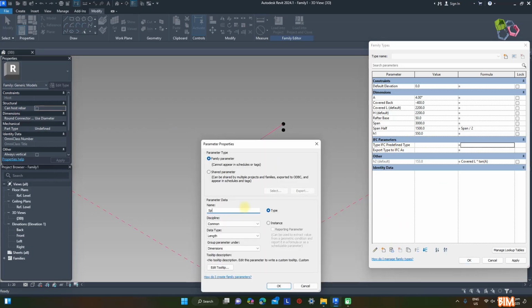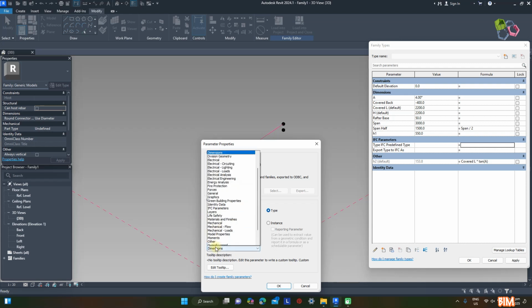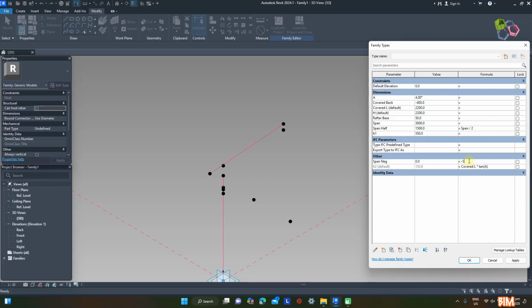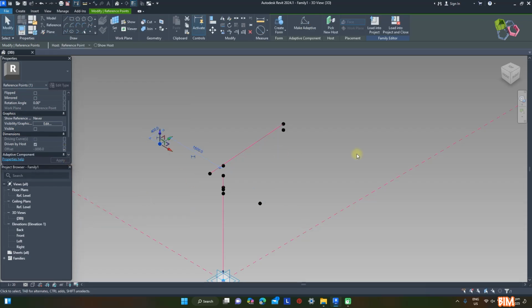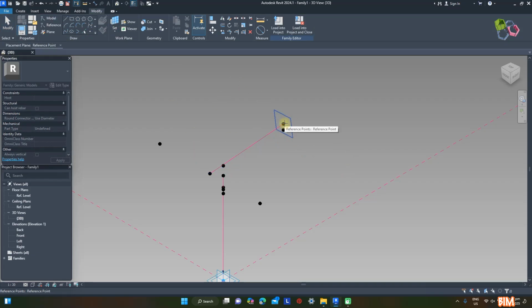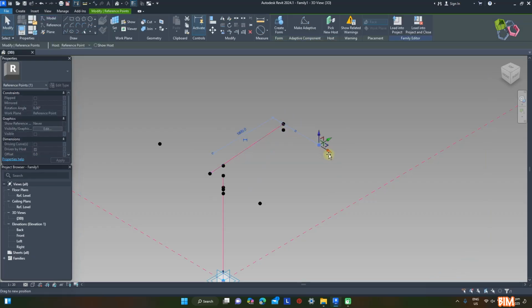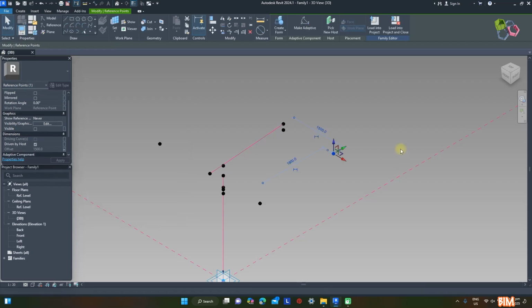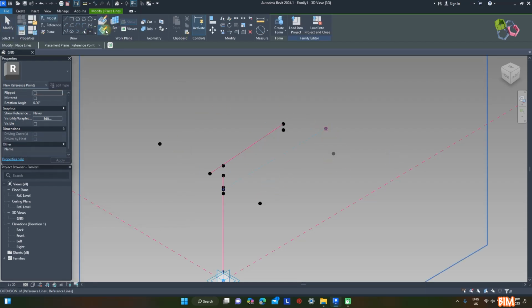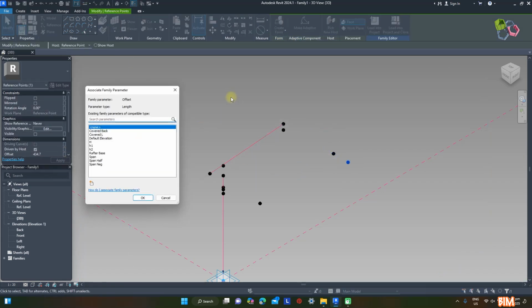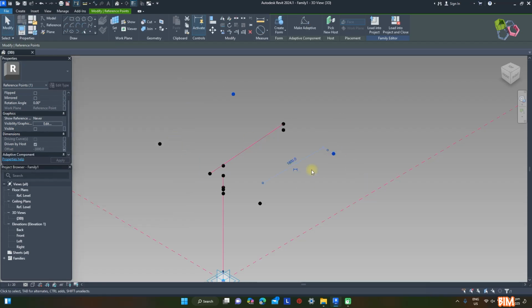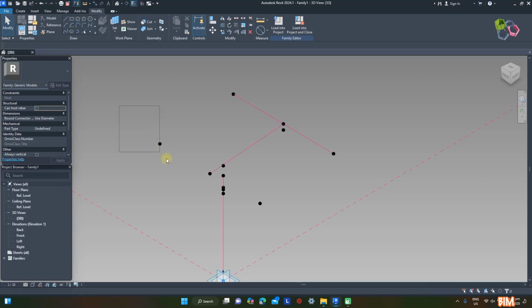Place each point for half span and full span on vertical working planes, controlled by span half as a new parameter, and another point placed on the vertical plane, due to point direction, should be controlled by the span negative length parameters. Repeat and reference 2 more points for the front as well. Then link to span half, and then link to the span negative parameters. Having 4 reference points forms a roof perimeter.